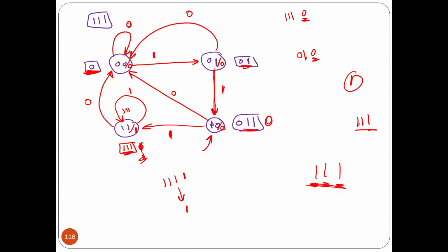So the question here is, in the very beginning, you assume you are in this state, right? Because this is the initialization I will do. That is why in the flip-flops, we have 2 special inputs for initialization. One is set, one is clear. That means before running the circuit, you have to clear it first to make sure in the very beginning you are going to be in this state.